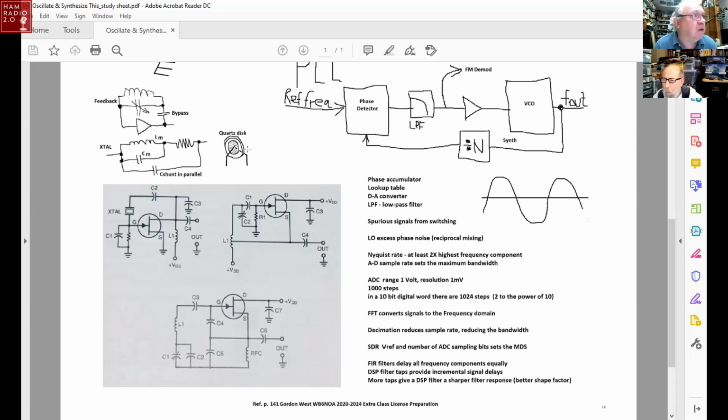The inertia of a quartz disc is called motional inductance. Inductance in electric circuits is just like inertia in physics of masses. And there's also a part of the operation of the quartz disc that is motional capacitance. That is, the solid quartz blank that makes the crystal can soak up high frequencies like a capacitor. And so if you look there, top left side down a little bit, this is the electrical equivalent circuit of a quartz crystal. It has motional inductance, it has motional capacitance, and that inductance and capacitance primarily sets the resonant frequency.